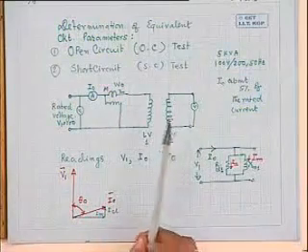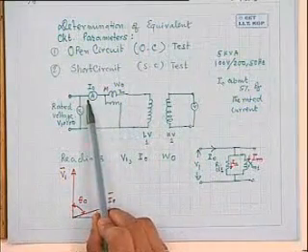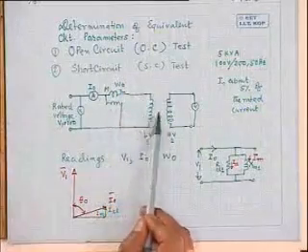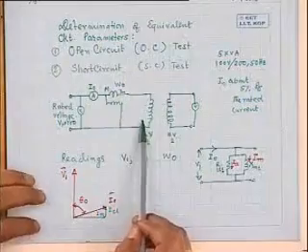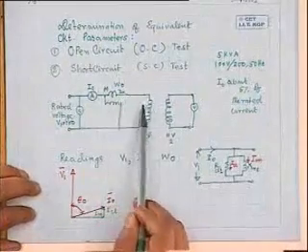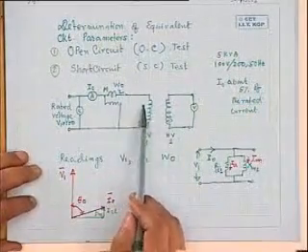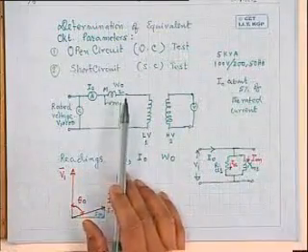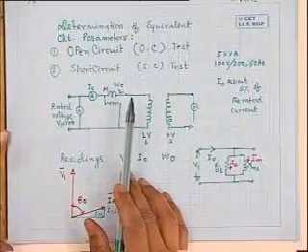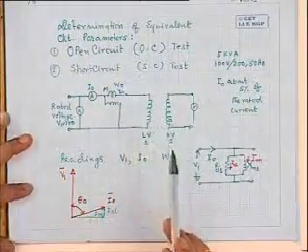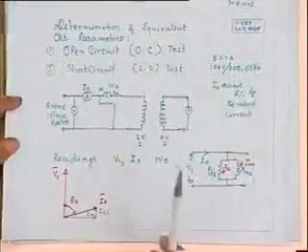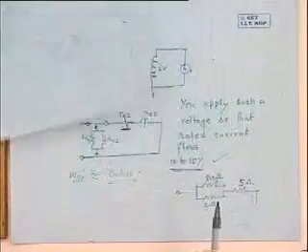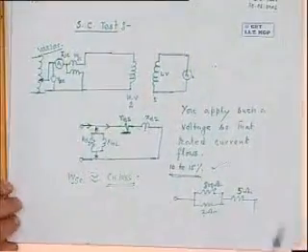As if it is recording only the core loss, because of the fact this current is quite small. The copper loss, this current is passing through the winding resistance and only through the primary winding resistance, no doubt. But that power loss we neglect compared with the core loss in this case, because core loss here will be quite high. Full voltage is applied. Okay, so that is one thing to note, and that's why this equivalent circuit is justified.